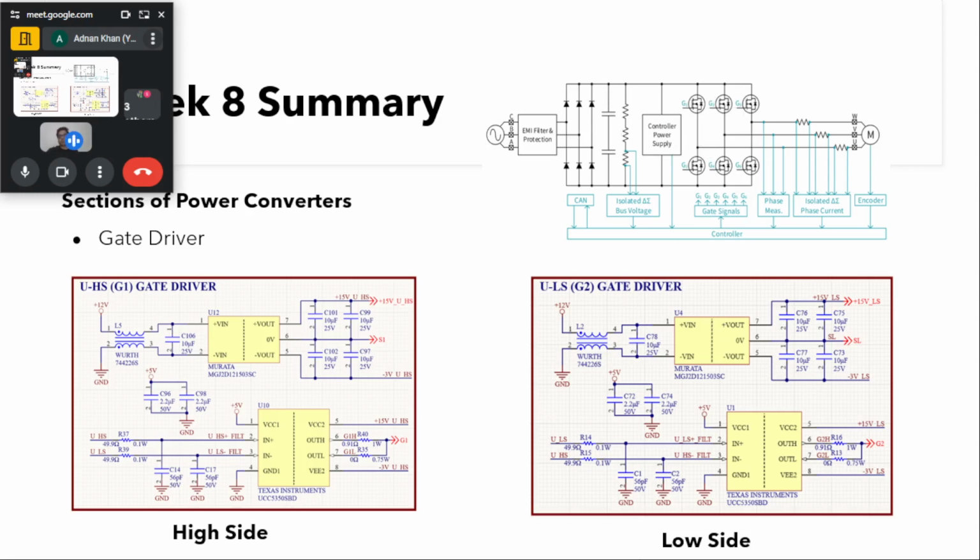You can see here that for the low side, in this application note, they have only one isolated supply, which gives the gate driver voltage of plus 15 and minus 3 volt in order to drive these low side switches.